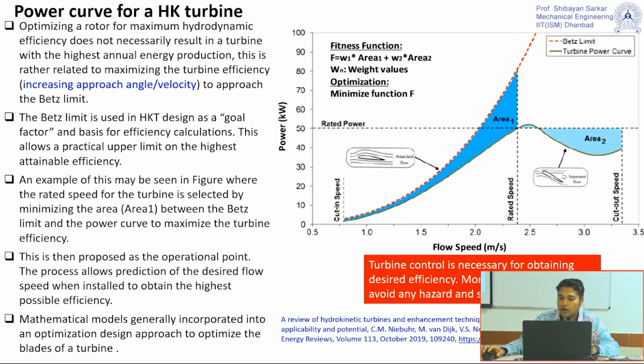So for this, what may happen is, somebody may change the pitch angle, somebody may incorporate additional parts, like a deflector, and some channel modification, say narrowing down, or maybe uplifting of the bed, so that the ultimate velocity you obtain exactly at the turbine blade will be higher.